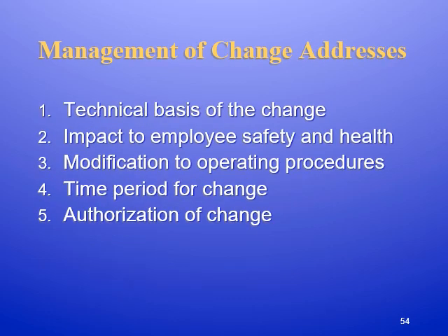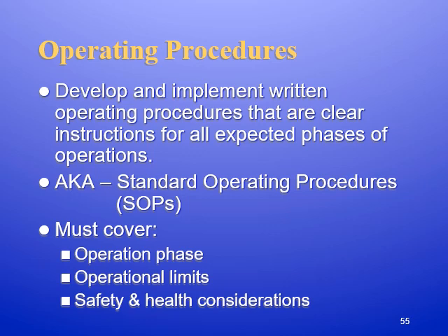So what management of change addresses is the technical basis of the change. And it looks at the impact to employee safety and health, modification to employee operating procedures, time period for change, and authorization. So what you need to do is develop and implement written operating procedures that are clear instructions for all expected phases of operations.